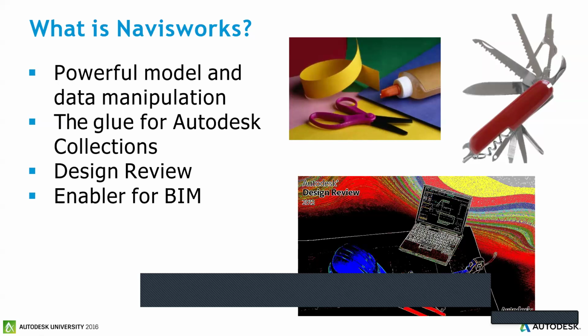Because there would be separate models, like the architectural discipline would have one model, the structural would have another, the MEP guy would have another, firefighting would have another, right? Whoever has made a mistake according to the holistic model will resolve those mistakes in his model and will again share the NWC file with you. In this way, the entire BIM process works, where you can easily get the information of the model, what was already there in Revit, as it is in the Navisworks part.